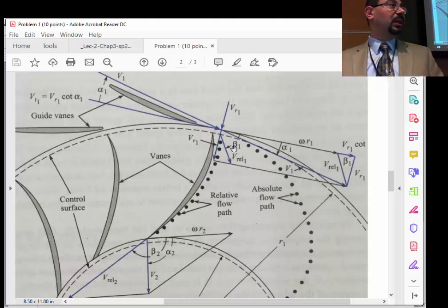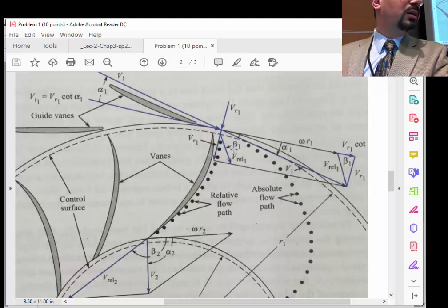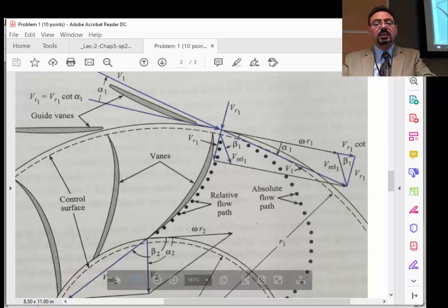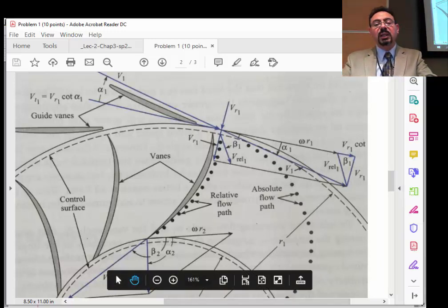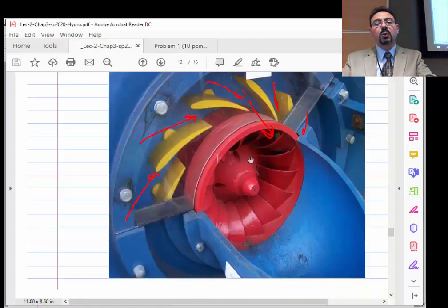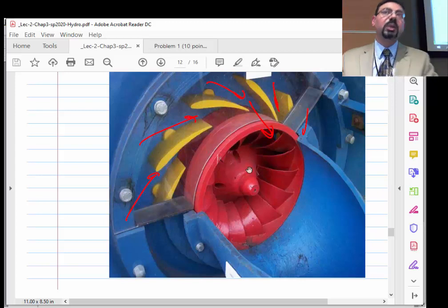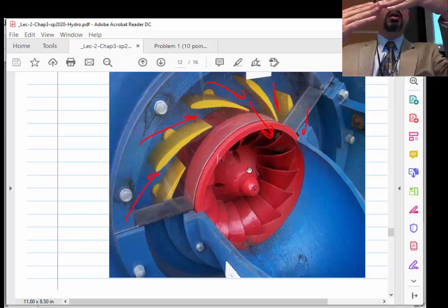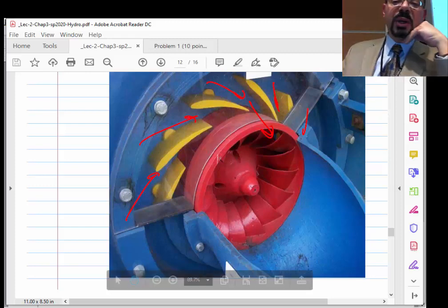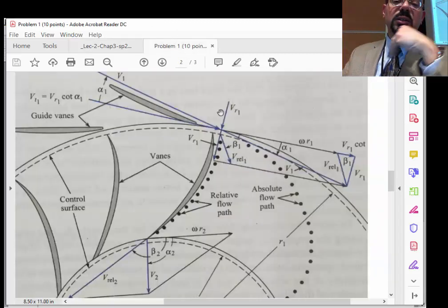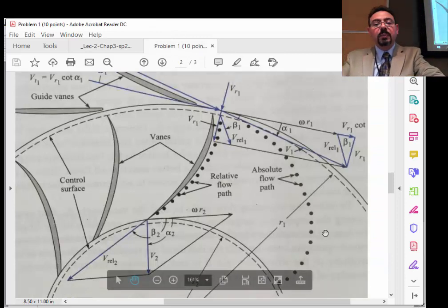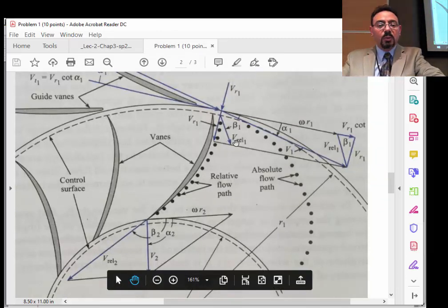And if the plate goes faster, the blade velocity could actually change W1. So the guide vanes, or the direction of the angle, need to catch up with the change of the load so that you maintain the right W1 direction. Otherwise the plates will perform horribly. If you don't come in at the right angle, you will end up separating and you'll have tons of friction and stuff.